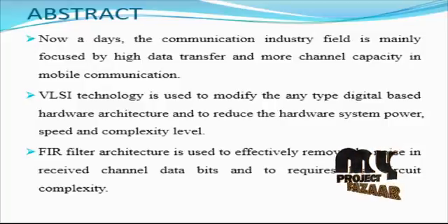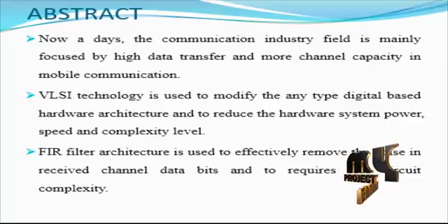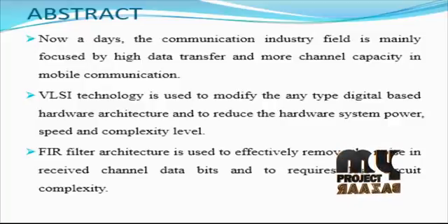The energy consumption of the system can be reduced by lowering the supply voltage. However, at very low supply voltage, the leakage energy increases and the net energy consumed per operation starts to increase. The minimum energy point depends on the activity factor and is also sensitive to process and temperature variations, and therefore the location of the minimum energy point changes during circuit operation. To track the minimum energy point, it's necessary to sense the energy consumed per operation at different supply voltages.